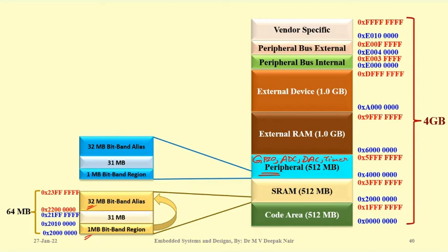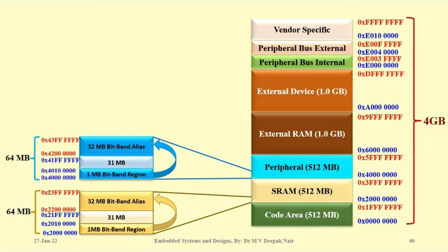So all these registers, GPIO, ADC, are 32-bit registers, but you can individually access each bit of these peripherals, because these peripherals are again bit banded. 1 MB of memory is bit banded to 32 MB of memory in the bit banded region. So what is the range of that bit banding region?